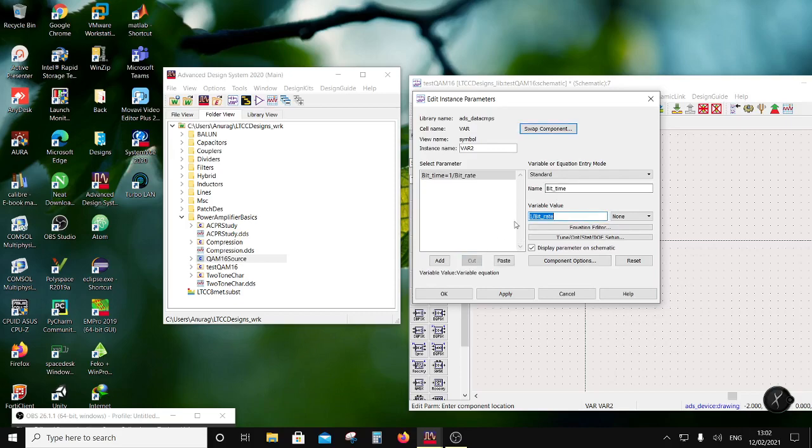Okay, and then symbol rate is equal to bit rate by 4, because now we are packing 4 bits, right, into one symbol. And then symbol time is 1 over symbol rate, right? And then samples per symbol is 10, so basically then t step.